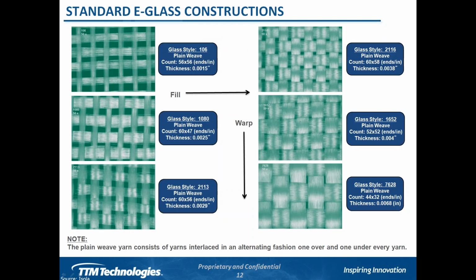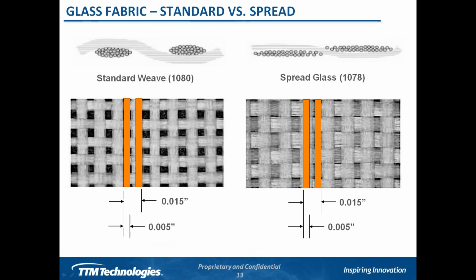We see a discrepancy between the properties for dielectric constant and loss tangent for resin versus glass, and that can become a big issue at higher speeds. So knowing that, glass is also available with different what we call spread characteristics of it.